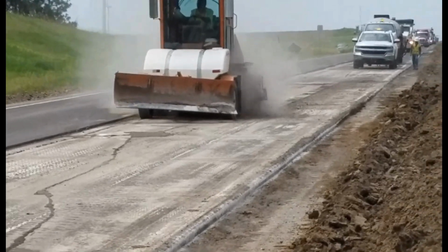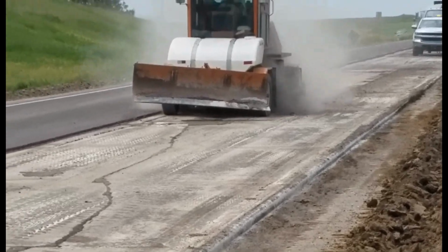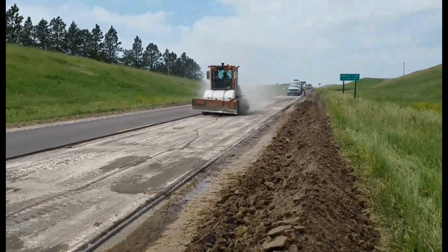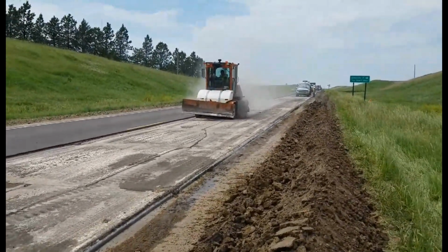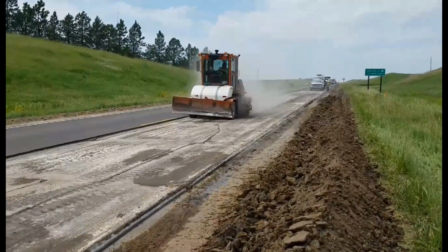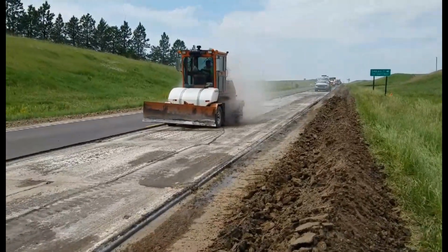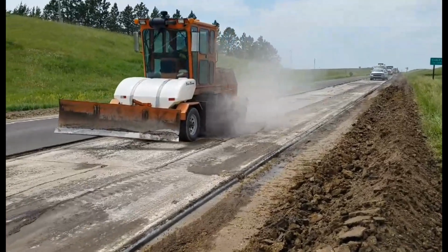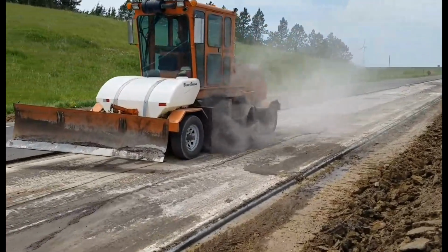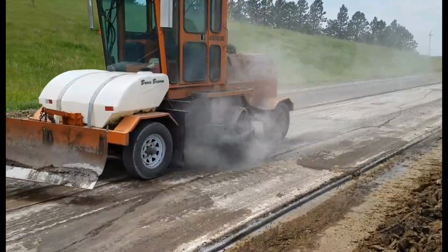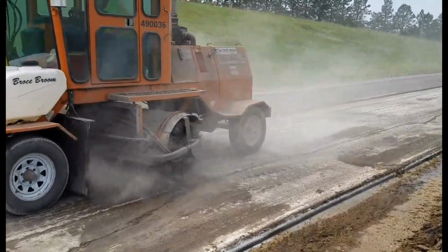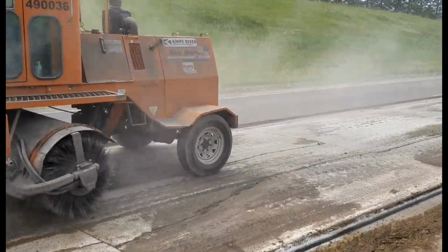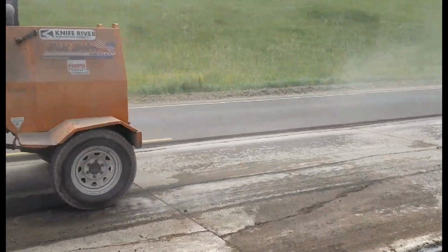After the trench is cut, a final pass with the last roller across the entire pavement to clean it up and get it ready for the tack. After he's finished, he leaves a nice vertical edge along center line from yesterday's paving operation.